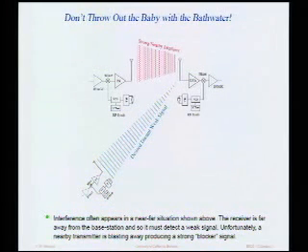Unfortunately, you're in a cafe and right across from you someone's also talking on their cell phone. And not only are they talking loud and not only are they annoying, but unfortunately their power amplifier is quite annoying too, because it's transmitting a lot of power, and the frequency could be very close to the frequency that you're receiving. So this is called a near-far situation. You're near an interferer and you're far away from the desired signal. And so this means that your receiver has to be able to deal equally well with small signals, which are very close to the noise, and large signals, which in fact excite nonlinearities in your receiver. So that's the key word, nonlinearities in your receiver. And this is something that we'll talk quite a bit about in this course.